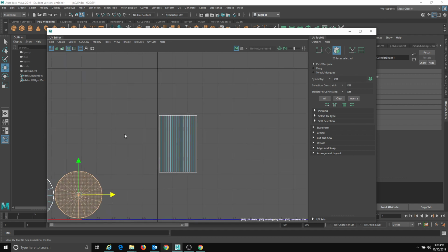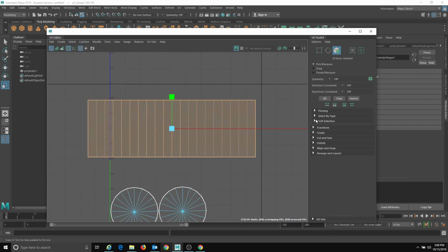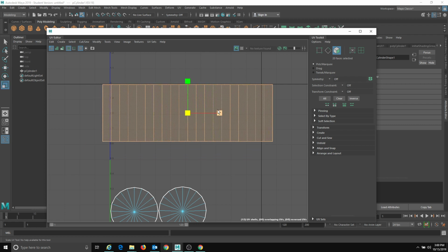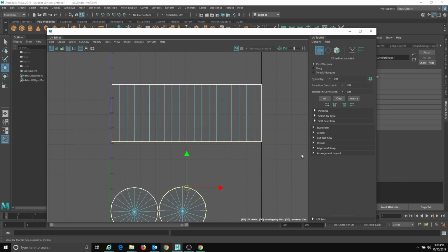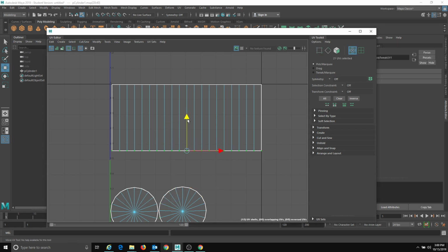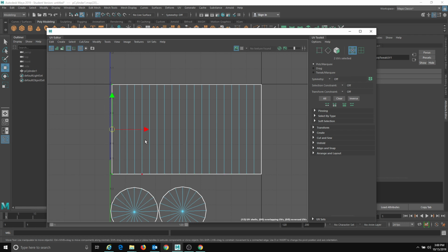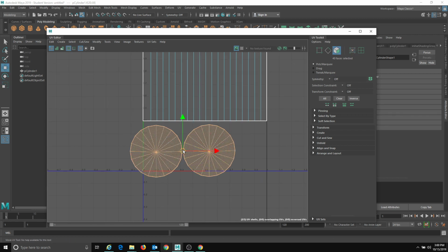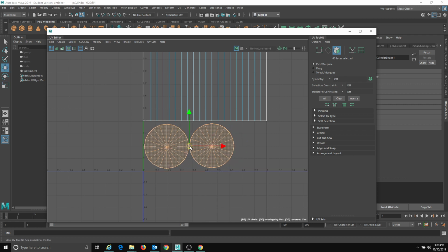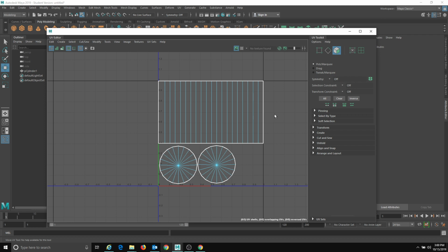All right, now that I have this, grab these, move these up, and stretch them out. I'm going to go to my UVs, drag across here, pull these down more, and I'm going to snap these edges to the sides of my UV space. All right, now that I have all this going on, I can scale these up as well. They're a little bit small. Okay. Now that I have something like this going on, I'm going to be able to